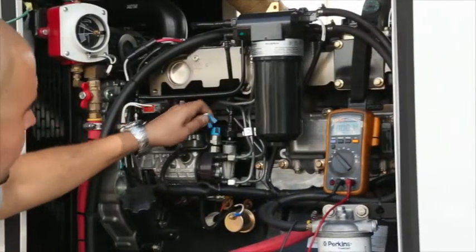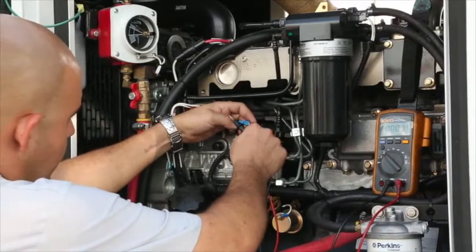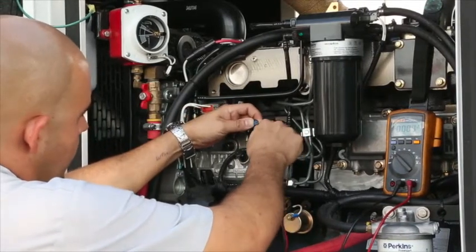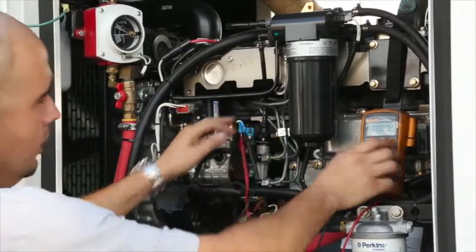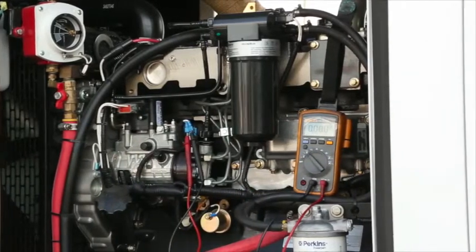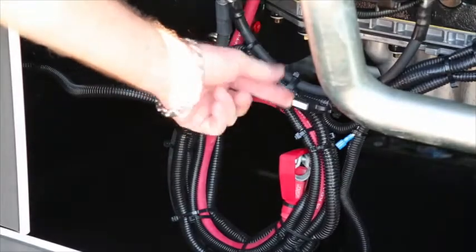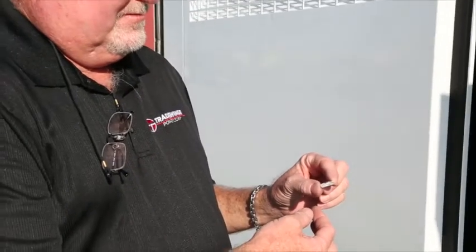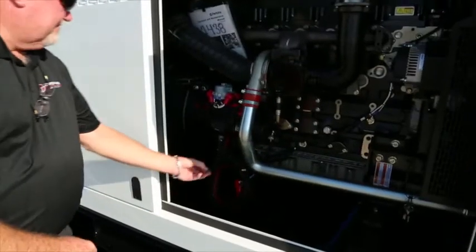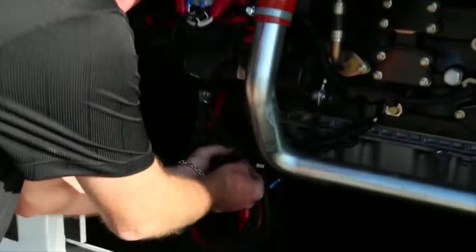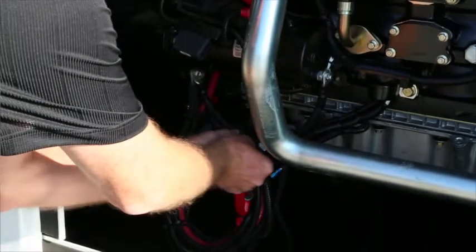After verifying the fuel connections are correct, the operator should then check if the fuel solenoid is operating. This check can be undertaken by connecting a voltmeter across the solenoid terminals as indicated. Having verified that fueling is not the problem, the operator should remove and check the ignition fuse. On the electronic governors, the ECU ignition fuse should be checked.